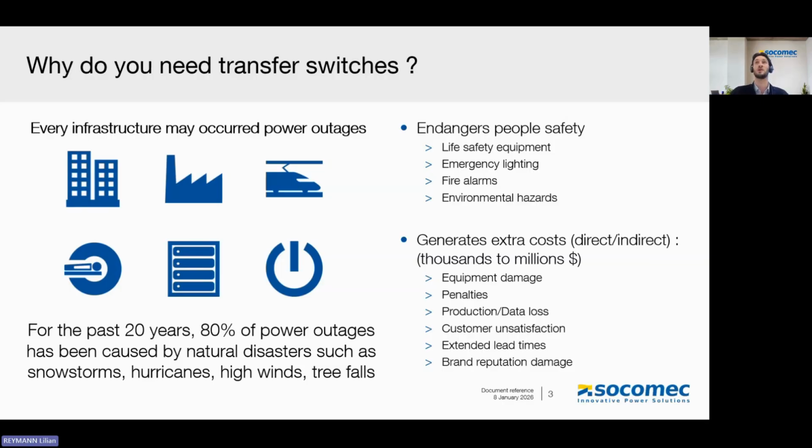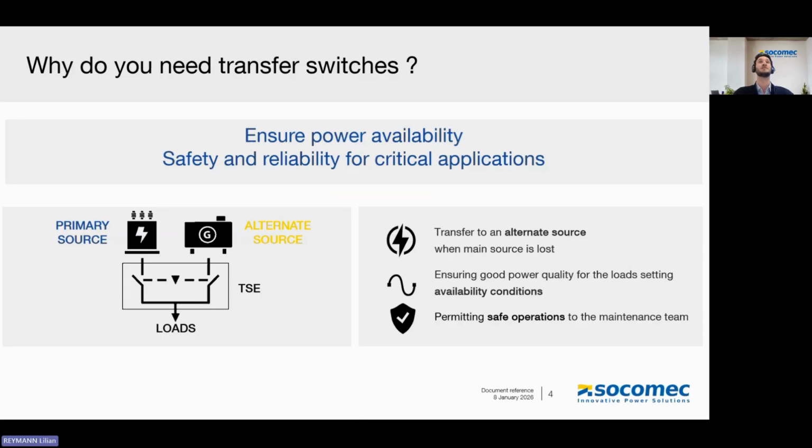Some installations require emergency systems, and it can be a problem if the life safety equipment, the emergency lighting, and the fire alarms are not supplied, so it can cause very dangerous events for people's safety. So for that, we have transfer switches. They are meant to ensure power availability, safety, and reliability for critical applications.